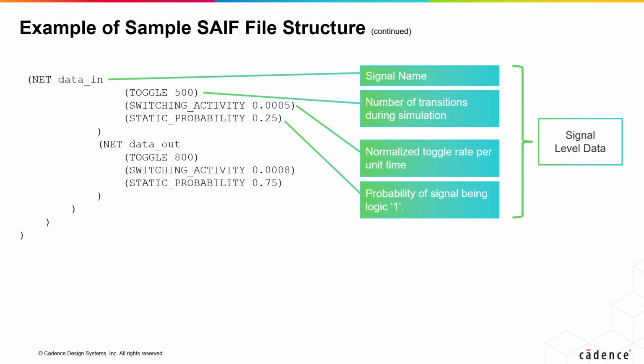Organizing the SAIF in this modular and descriptive way allows engineers to trace hotspots, validate power intent, and accurately document real simulation activity. This structure highlights the systematic and user-friendly characteristics of Switching Activity Interchange Format, or SAIF, making it vital in any power-aware digital design workflow.